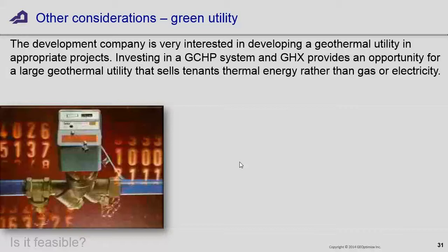We're just connecting all of the different buildings up to a common ground loop. They happen to have a hockey arena that the town owns, and when the development gets big enough, they'll put a water-cooled condenser on the refrigeration plant, dump that heat into the ground loop, and then the houses will take advantage of that instead of building more ground loop. That's the kind of thing you can take advantage of.